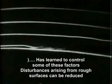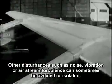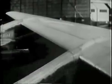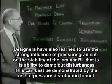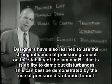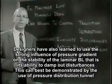The designer has learned to control some of these factors. Disturbances arising from rough surfaces can be reduced. Other disturbances, such as noise, vibration, or airstream turbulence, can sometimes be avoided or isolated. Designers have also learned to use the strong influence of pressure gradient on the stability of the laminar boundary layer, that is, its ability to damp out disturbances. This can best be demonstrated by use of a pressure distribution tunnel.